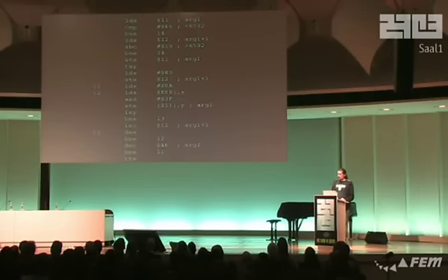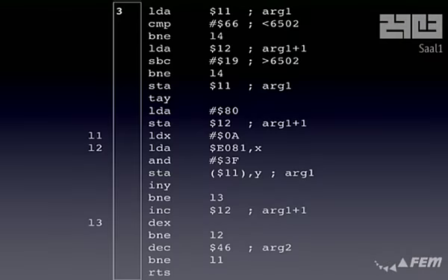If we go through this real quick, load from 0 page takes 3 cycles, because you have the load, you have the operand, and then you have the load from 0 page. The compare has 2, because the instruction is 2 cycles. It doesn't do any other fetch. This one has 2, because it's also a 2-byte instruction. If the branch is taken, there's an extra cycle there. We've had this one. This transfer is only a single byte, but we have a minimum of 2 cycles.